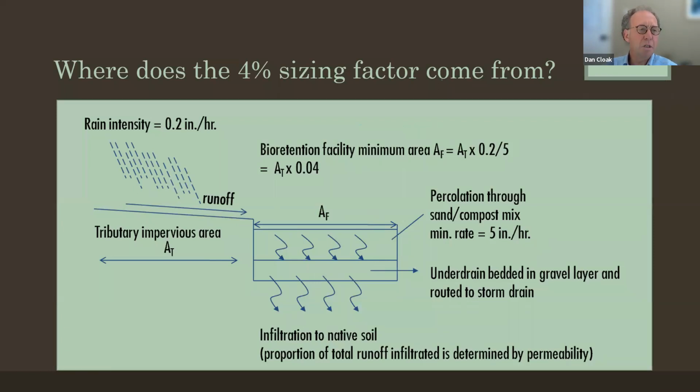I imagine that happens in some cases. The implementation of bioretention in tidal zones is something that really needs to be looked at carefully if you're doing a project right at the shorefront in a tidal zone. But otherwise, in most developments, that 18 inches is going to make sure that you don't have much upwelling, or if you do, it's going to be very transitory.